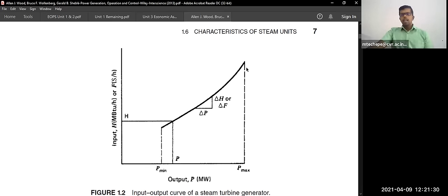If you exceed 100 megawatt, that is, go beyond 105, the winding inside the alternator will be affected, and the lifetime of the generator will also be affected.